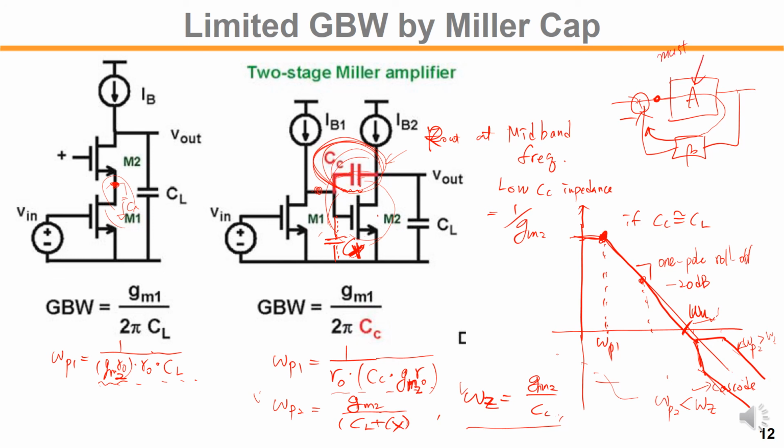So this amplifier here must have a single pole below omega u. So this beta is just a constant. So beta is below 1, equal to 1 for this case. So this is a kind of feedback circuit requirement. A typical amplifier used in a feedback system to generate a stable gain.